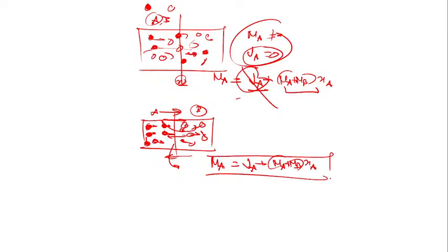No, the direction of flow is not from high to low. A will transfer from left to right and B will transfer from right to left, but not because of that only; the bulk is also moving. So some of the species get transported due to individual characteristics and some due to bulk flow. Some contribution to the total flux is due to individual characteristics and some because of bulk flow. Both will contribute to the total flux. Is this clear?